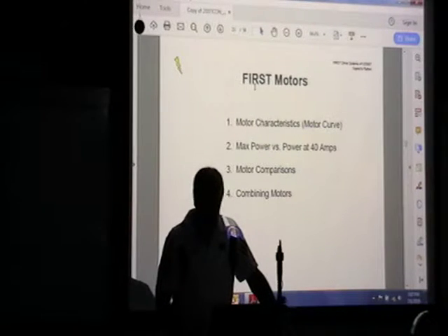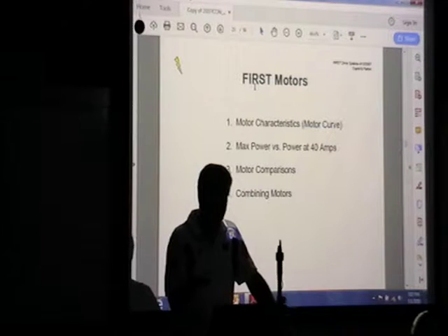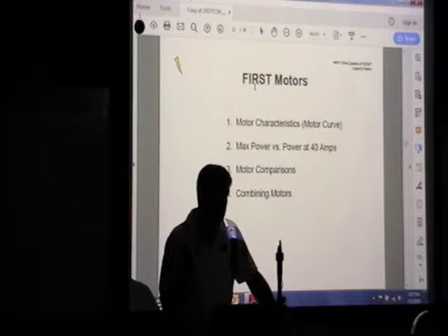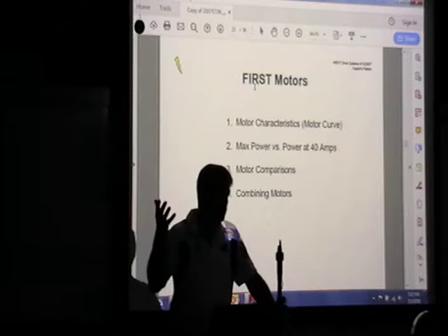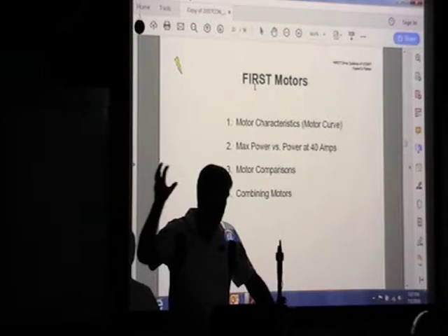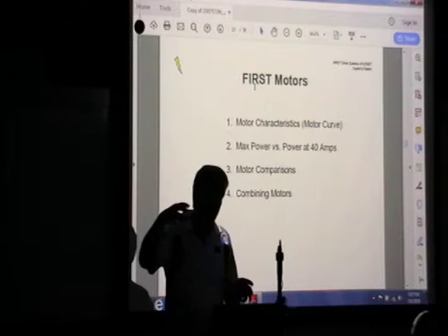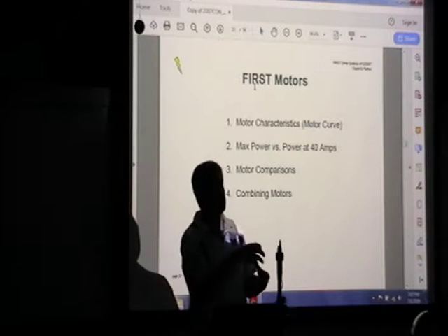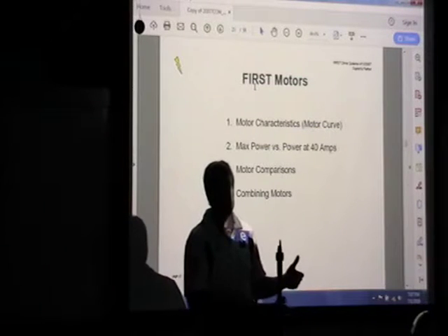So when you're designing your mechanisms, you've got to go through the exercise like we talked about last time with your simple systems and your pulleys to figure out what the load is back at the motor. Whatever you're trying to do is the load out the end of the actuator or mechanism. You calculate that back through any lever arms that you've got, you calculate that back through whatever you've got in your pulley ratios, and that's what the motor is going to see.